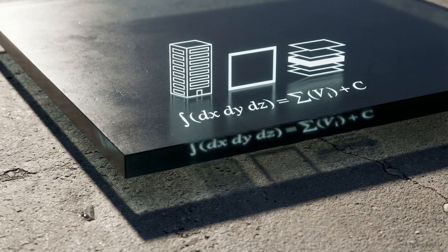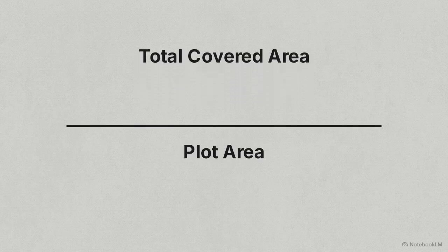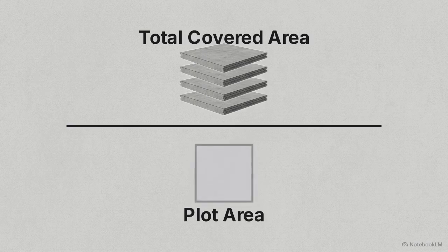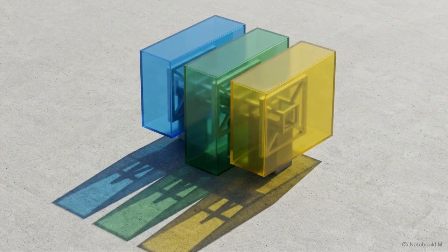All of these individual spatial limits feed into a single mathematical output regulating real estate density. This chart shows the floor area ratio, or FAR. It is the quotient obtained by dividing the total covered area, or plinth area, on all floors by the total area of the plot. This density calculation is tethered to the structure's occupancy, or use group, which is the principal purpose the building is intended to serve.